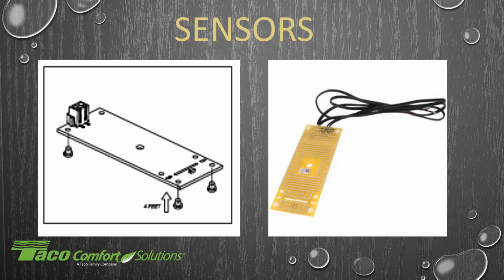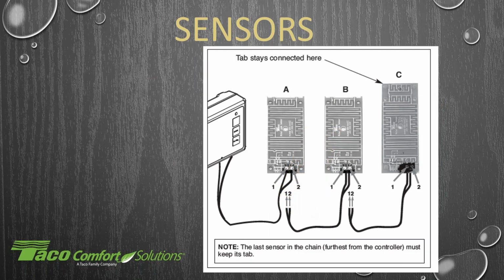So, very interesting. I think we try to make it a little bit easier to control and to see what's going on with it. When you are running your sensors, we run them in a daisy chain. So on the terminals, you'll see 1 and 2. You want those wires to go 1 and 2 from one to the next. And what you're doing with the sensor looks like the picture you see down at C.